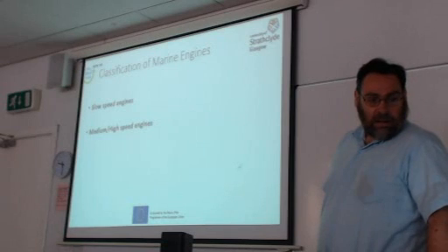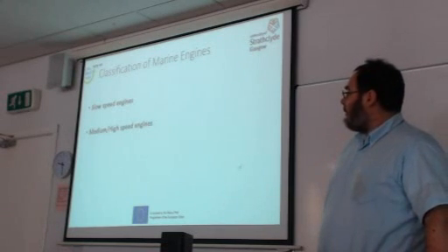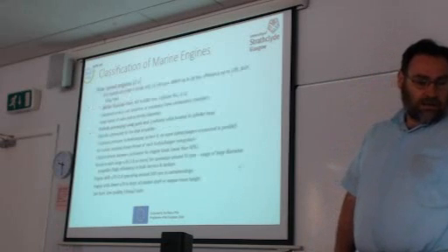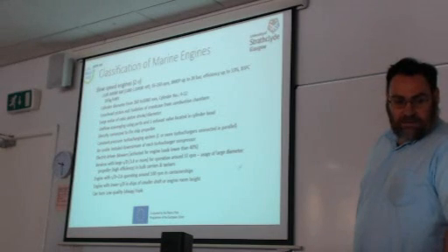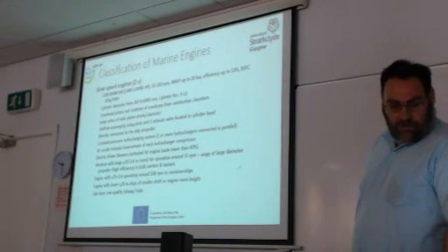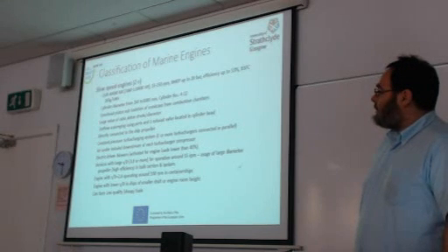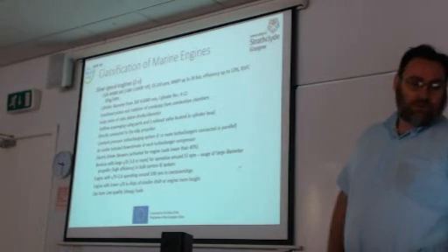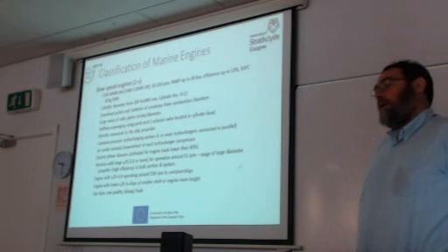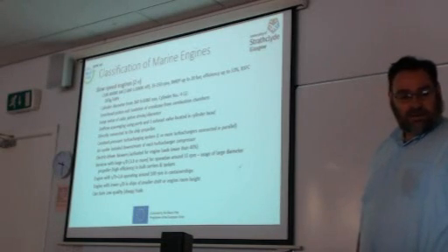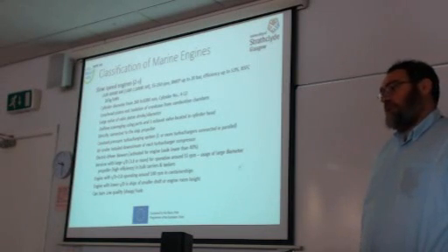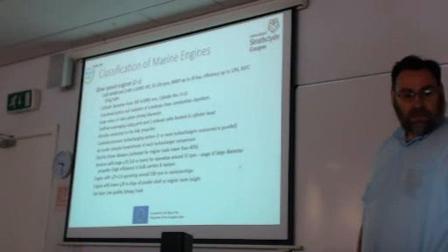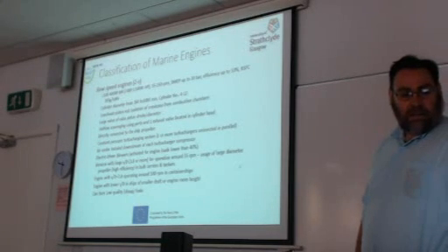The marine engines, the engines used onboard ships, can be slow speed engines or medium and high speed engines, and then there are some advantages or functionalities of each category of engines. So for example, we know that the slow speed engines are used in merchant ships, large ships. They can provide large powers. They are the most efficient thermal engines, obtaining efficiency up to 53%.